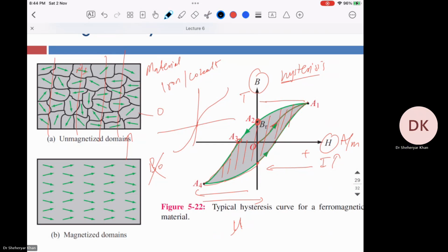So it's a constant ratio, right? Now, for iron, if you increase the current and compute the H, and then multiply with the mu R of the iron, then you will get the magnetic field. So through the current, you compute the B. And you see that when you increase the current, the magnetic field increases. It's somewhat a straight line.